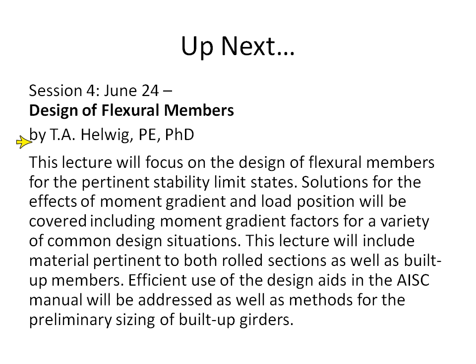The key response I want to give, and I almost feel like a bit of a politician here, is I just want to indicate what you're trying to do is resist twist. So if you can develop some type of a mechanism between the tension flange and some type of a brace point, maybe it's even coming into the neutral axis, out of plane brace point, but as long as you can sort of try to develop some type of resistance to twist, you're going to get a nice bracing solution.